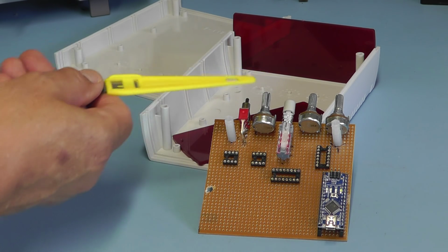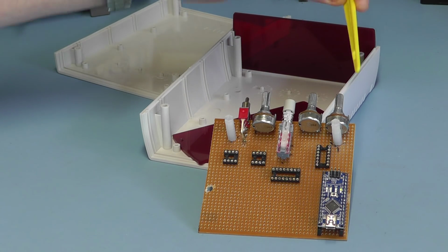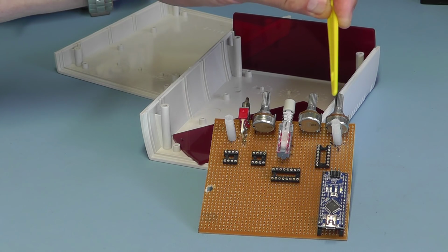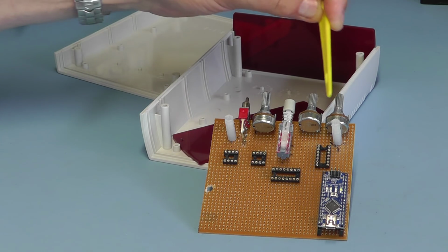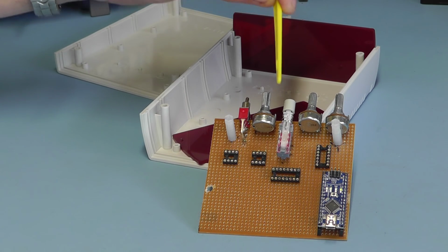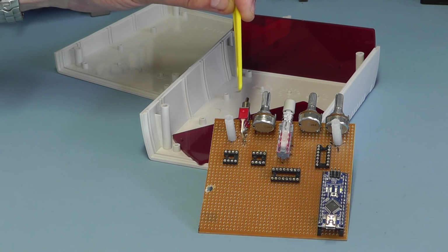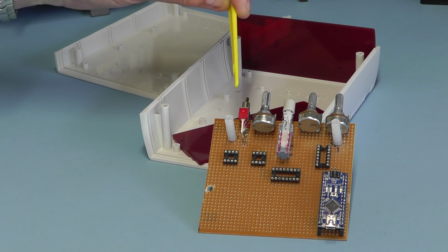And then I've just temporarily positioned some of the potentiometers here at the front. I'll have the frequency adjustment there, so I'll have the coarse and the fine frequency adjustment. I thought I might use a push button there to switch between sine wave and triangular wave, and this control here, I think I'll use that as the gain control, and the switch there, I think I'll use a simple switch to switch between square wave or sine wave output, switching the output.